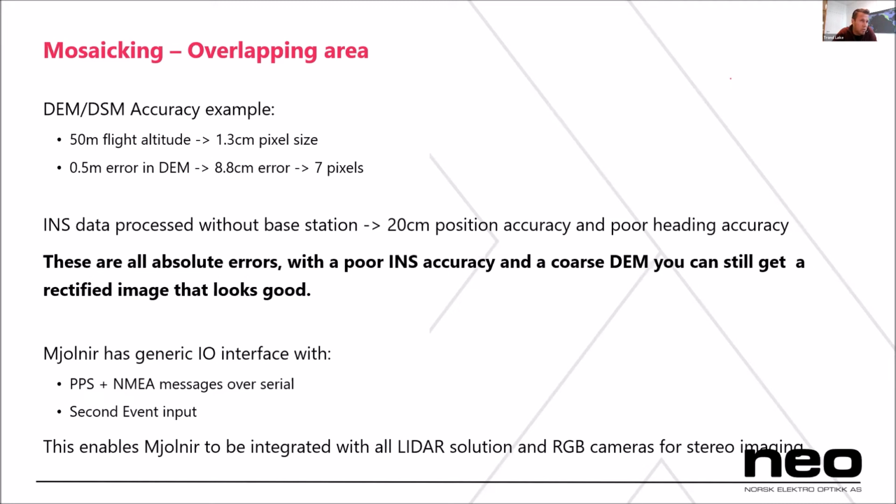If you are using a real-time INS solution, you can use Omnistar or TerraStar to get corrections in real time as well. You only need that if you have a high specification for the absolute accuracies in the GPS position. The image will still look good. The rectified image will look nice even if you don't have the absolute high accuracy.